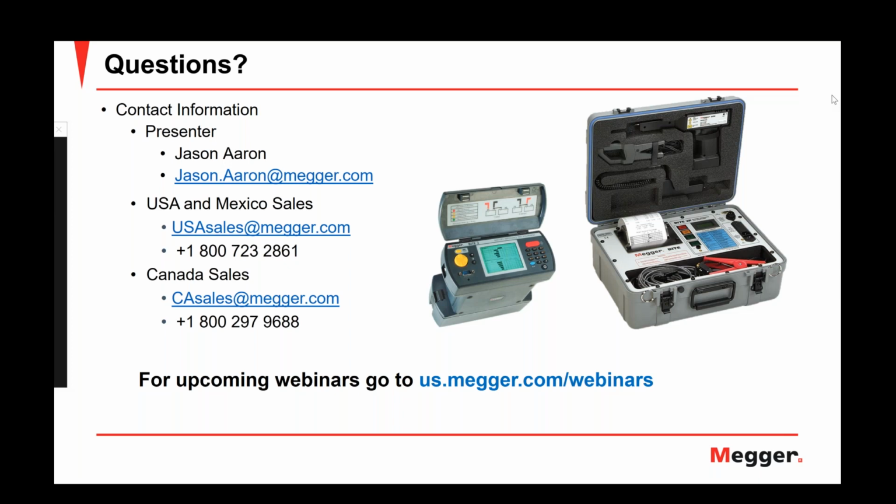All right, thank you. Additionally, Sanket, would I be able to run an impedance test with the BITE 2 on a 480 volt battery bank? Again, this comes down to the way the instruments function. With the BITE 2, you connect the current leads across the whole battery string, and then you take measurements across each cell. It's not the case with the BITE 3. On the BITE 3, you can test the same way irrespective of the voltage rating of the battery bank. But on the BITE 2, there is a voltage limit of 250 volts, so you cannot connect the current leads on a string which is greater than 250 volts.